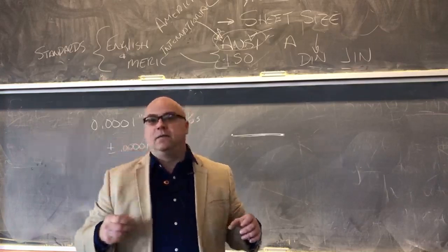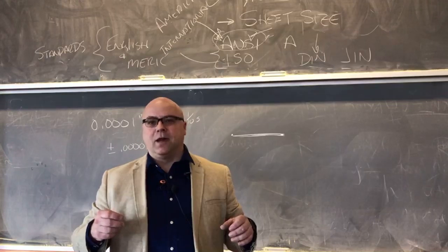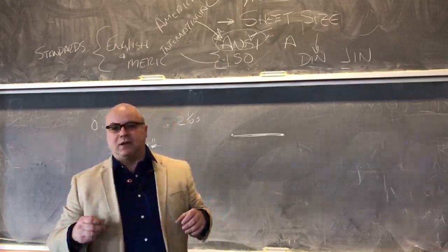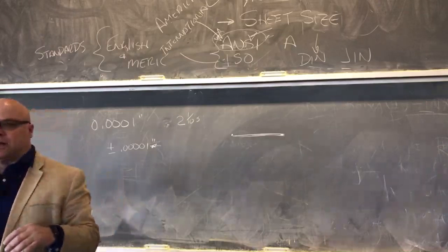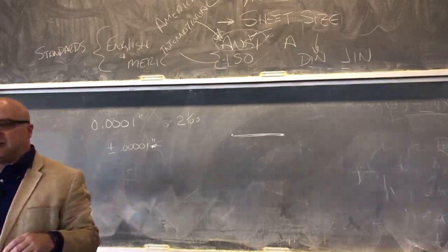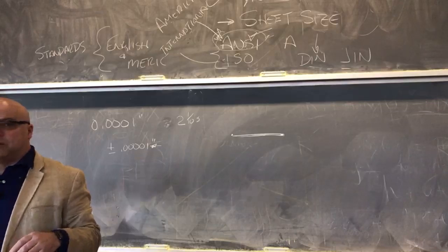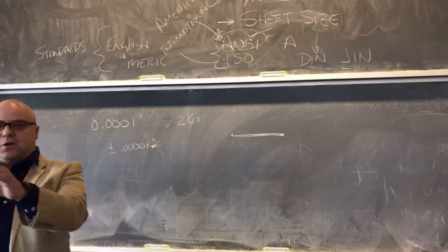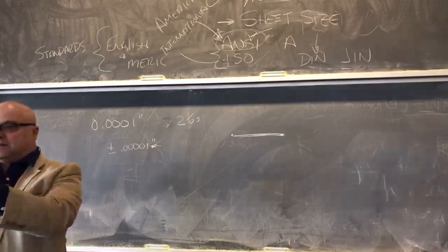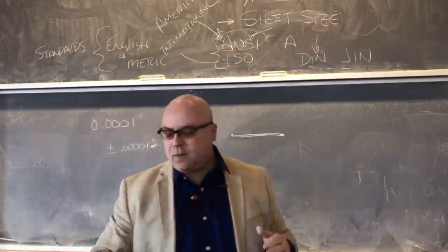Yeah, we're going to ignore temperature now. Actually, we use temperature as a tool sometimes when they put aluminum rivets and aluminum airframe parts for airplanes to put the skin on the airplane. Sometimes you keep the rivets in the freezer. And so when they're in the freezer, they're smaller, right? And so then you put them in the hole, and as they warm up, they expand. So you tolerance the hole so that you just slide it in when it's smaller and it expands. And so you do stuff like that.